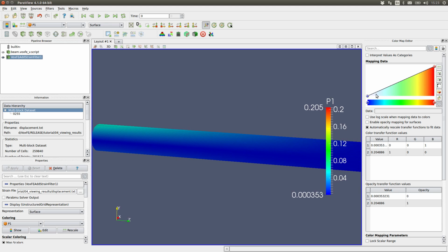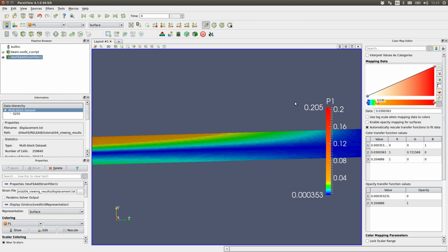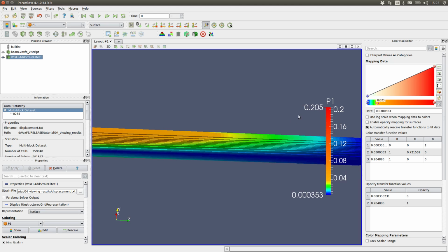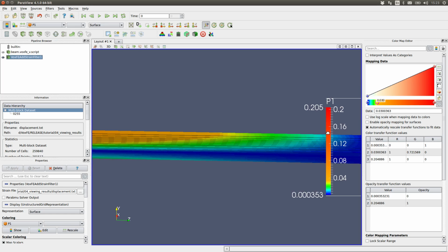So the first thing to try is you can add extra points in here. What we've got is all our data really is down here. So what we can do is click in this scale and create an extra point and drag everything down so that there's a whole lot less blue going on, and that works as a quick way of changing the range. But actually the effects are still rather strange, because the values that the range itself is giving us aren't actually much good.